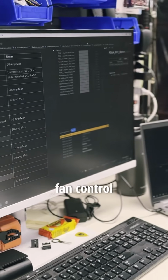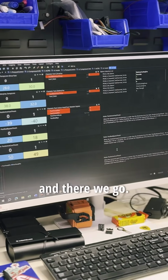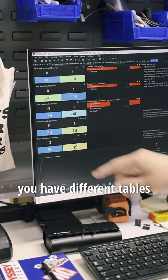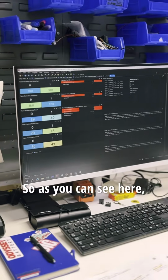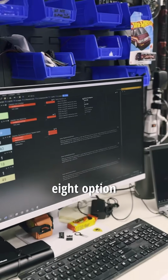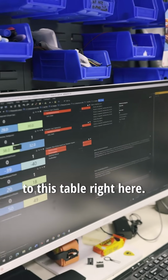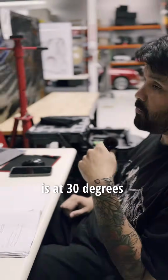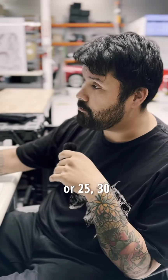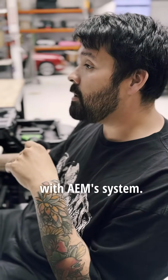So for cooling fan control, go to condition, fans, there we go. Here you have different tables so that you can set your temperature limit for when you want that output to actually activate. As you can see here, PDU4 channel 8 option, battery cooling fan, that'll be the output that's connected to this table right here. So it can be activated when battery temp is at 30 degrees Celsius, or 25, 30. Full on control with the AEM system.